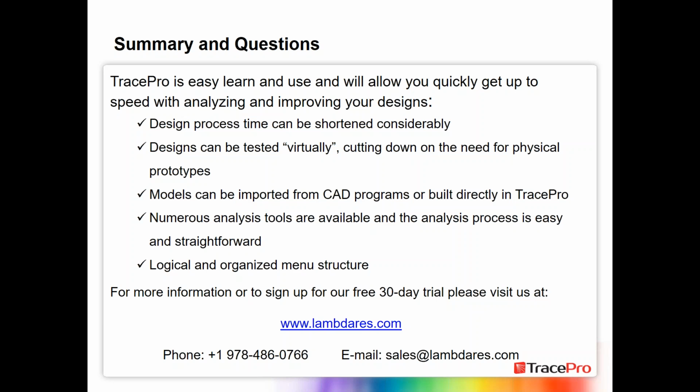Models can be imported from CAD programs or built directly in TracePro, you don't necessarily need a CAD program. There's also numerous analysis tools available, things like the irradiance and illuminance maps, the candela plots. There's luminance plots in TracePro as well, and photorealistic rendering, and a lot of other tools. And that this analysis process is easy and very straightforward. And lastly, we've tried to provide a logical and organized menu structure that lets you build a consistent workflow and really speed the process. You're not looking for buried items in menus.